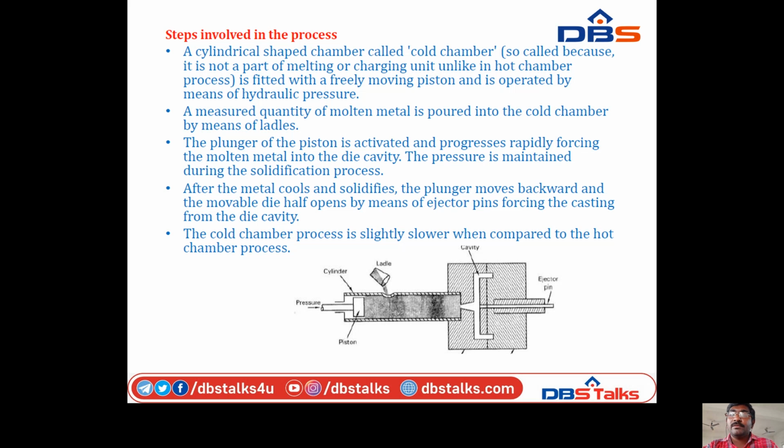Steps involved in the process. A cylindrical shaped chamber called the cold chamber, because it is not a part of the melting or charging unit, unlike in the hot chamber process, is fitted with a freely moving piston and is operated by means of hydraulic pressure.